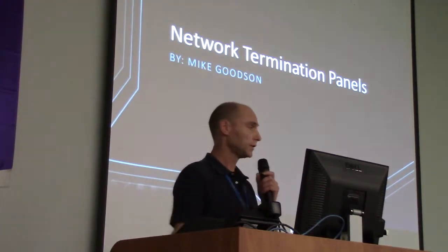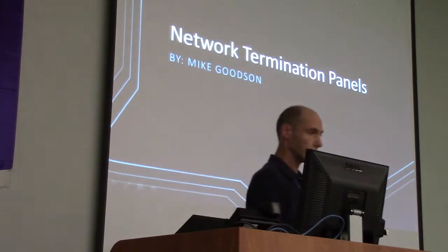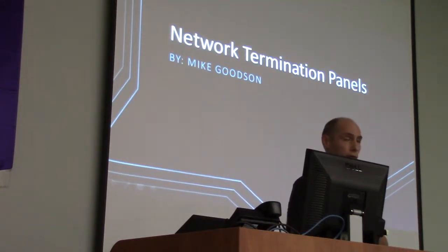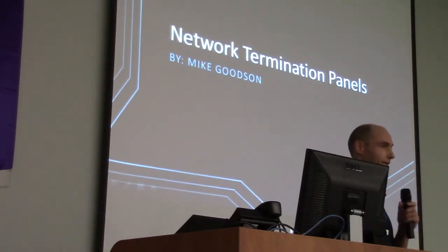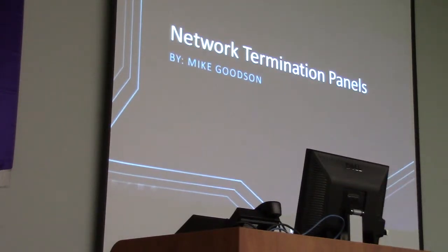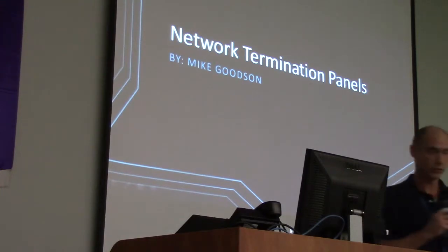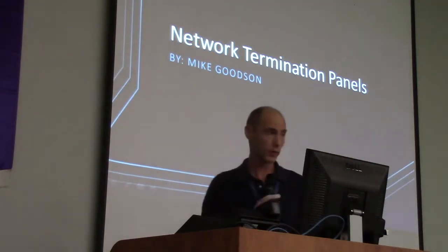So first off, who has ever seen or knows of a termination panel? Anybody else other than cable? I know all of us do. Well, you already went through cable. So this is essentially the board that you all get to do with cabling, and this is a couple of the blocks that I'll be talking about. So, a 66 block and a 110 block. Those are the major ones for termination that you'll find doing networking.